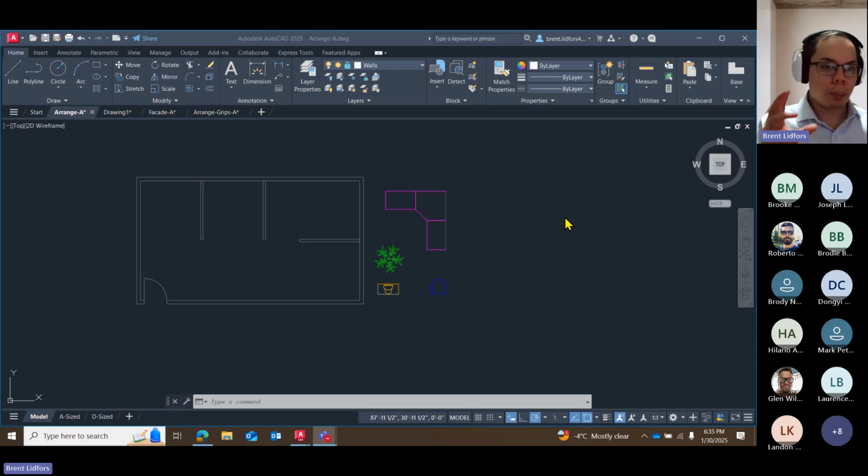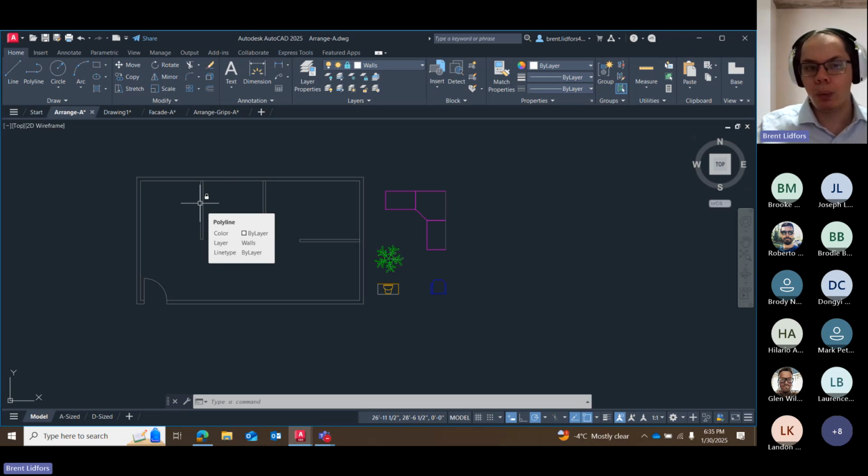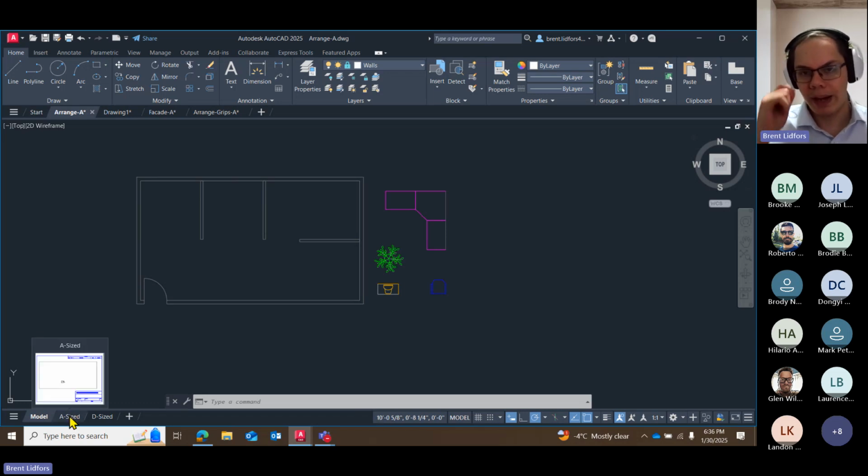Yeah. What probably happened was that you printed it from the model space. If I print while viewing the drawing space as it normally is, it's going to come out weird because AutoCAD will try to figure out what the dimensions of the drawing are supposed to be. So instead of being in the model space, you need to go to the layout. At the bottom left there should be a tab called A4 or something like that.